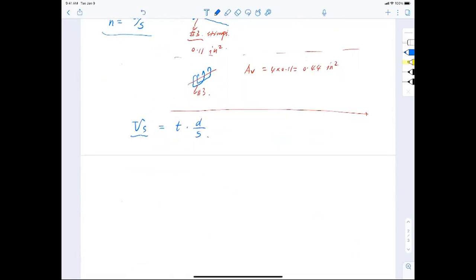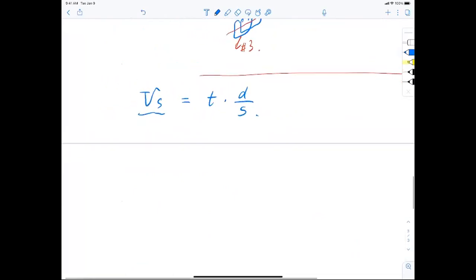That is how we estimate shear for the reinforcement. We literally count the stirrups, but we do it in terms of calculation: T multiplied by d over s. Now d is something we know, the effective depth. The critical design parameter here, you notice, is s.